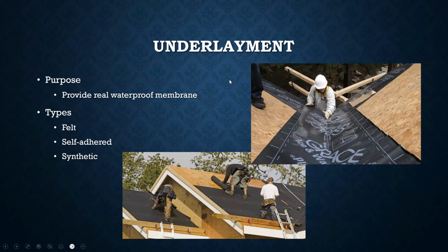So underneath your roof or underneath those shingles and all those things, you're going to be worrying about your underlayment. The underlayment's job is to waterproof the roof. The shingles' job is to protect against UV, flying objects, falling objects, and get most of the water off the roof. But ultimately, the true waterproof barrier is the underlayment.